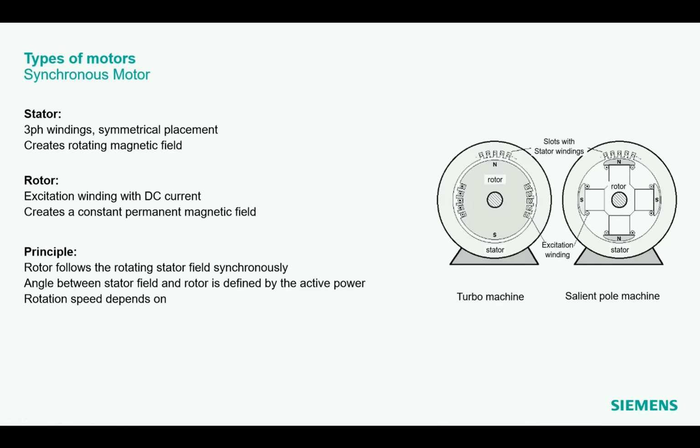And the more noses we have, poles or pole pairs, the slower is the frequency. And also here the rotor frequency is just the synchronous frequency divided by the number of pole pairs. And this is exactly the value when they are in synchronism, because the rotor is as fast as the magnetic field that rotates around.